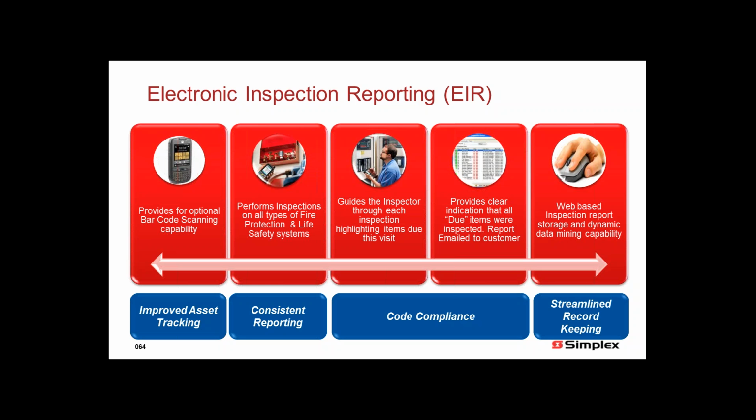And then provide all of this information very clearly to the owner, to the civil defense, and give it to them electronically, where we can be emailed or go up to a web-based portal where it can be easily retrieved, and maybe even use that data to start to run reports, where if a building owner wants to know how many systems do I have in total, how many smoke detectors is that across all of my facilities? You know, knowing that you told me that 26% of my smoke detectors are going to fail in 10 years, and based on how many devices that I have in total, you can start to run reports and maybe start to budget monies to replace those devices or what have you.